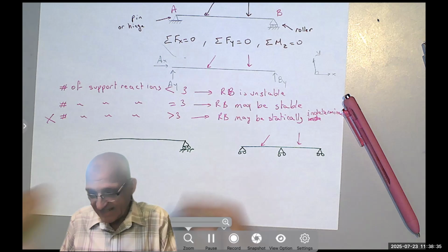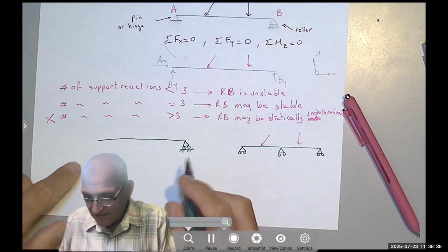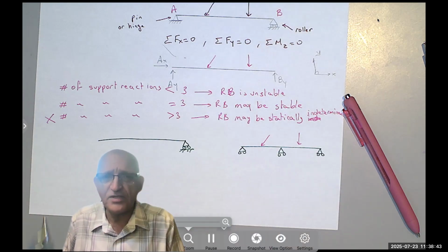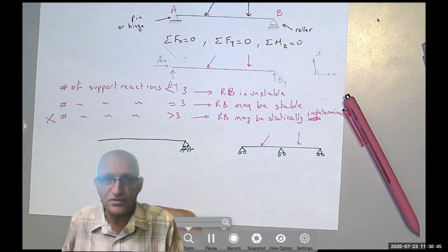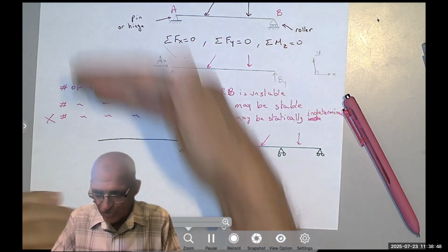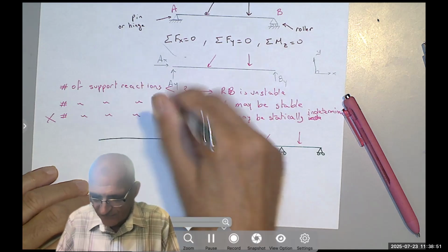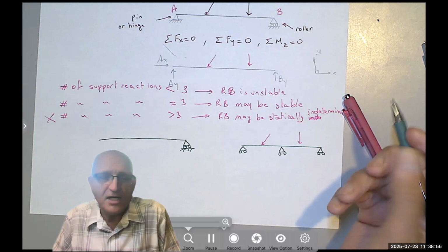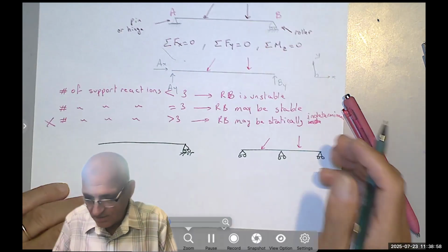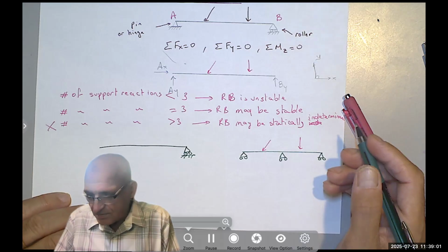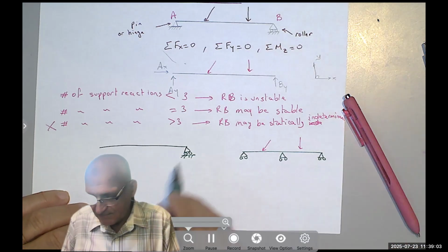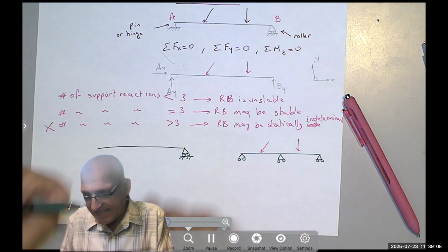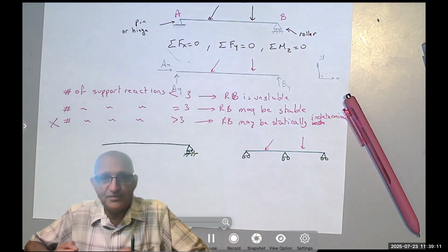Okay? And using statics I cannot find the x components as well as the y components, because I only have three equations of equilibrium, not four. So I know that, for example, if these loads are vertical, the reactions are equal, but I don't know how much each one is, right? So that's why we say the roller here is to relieve that stress, so the body can extend a little bit without being compressed.